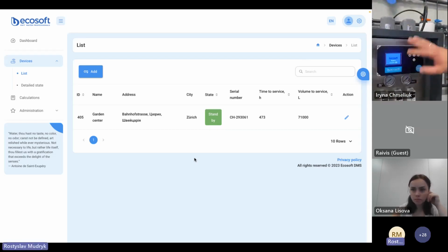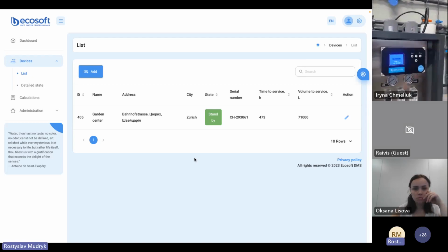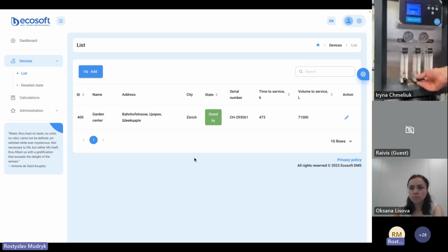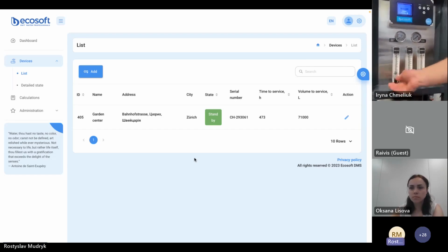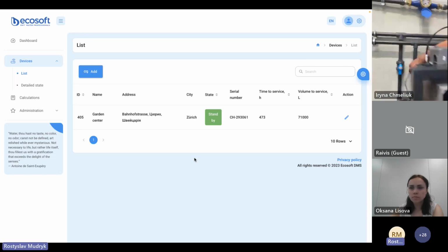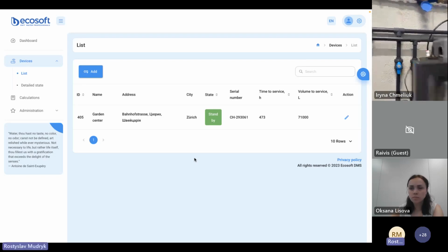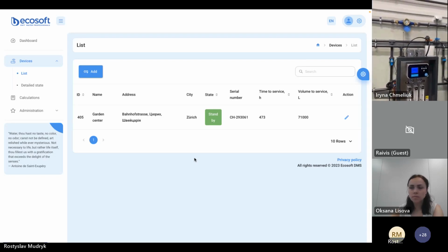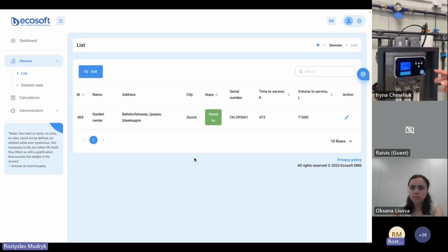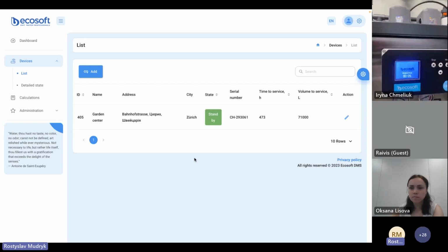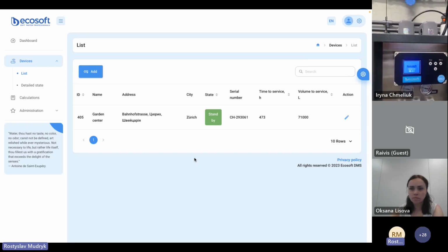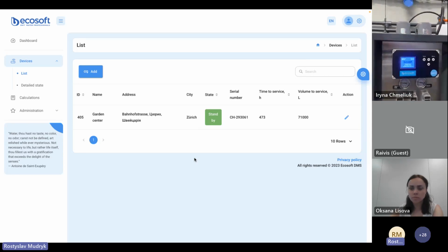So basically, now the system is in standby. Before the adjustments, we have to open all the recycle and the drain, and then we start the system. We open the water supply and let the system run. Before every start, the system waits for 10 minutes. The solenoid valve is open, and after 10 seconds, the pump starts.